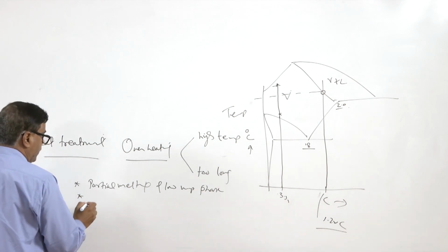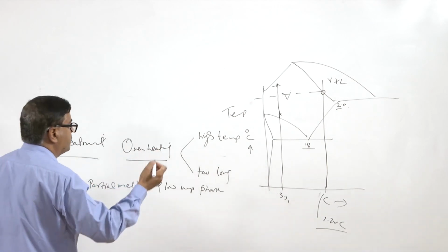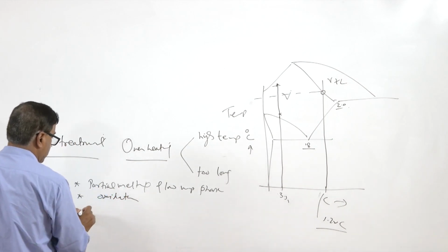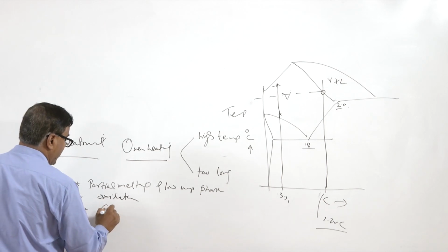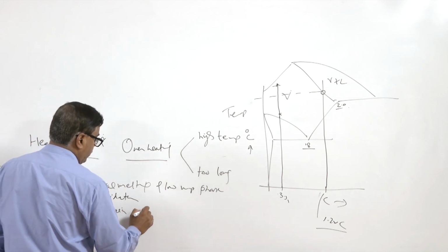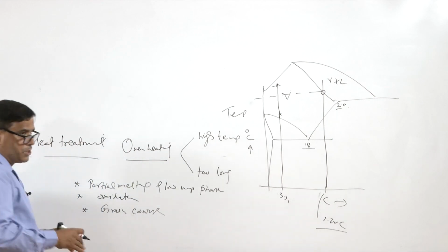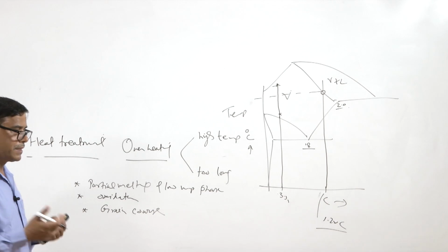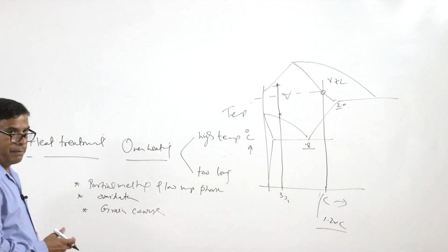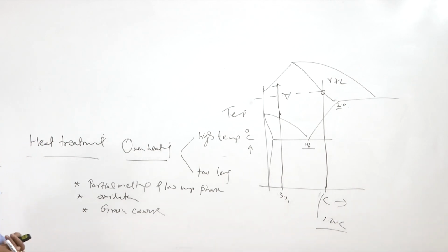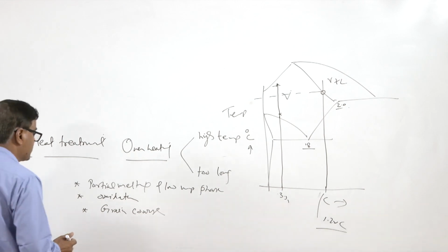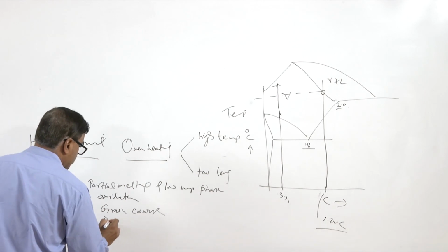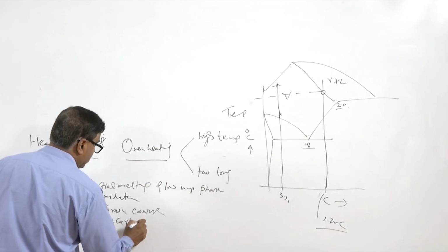Apart from this one, heating to a high temperature for long can lead to oxidation of the metal surface. It can also lead to excessive grain coarsening in the form of coarse-grained austenite, which can increase the hardenability and produce martensite in place of the fine pearlite which would otherwise be needed. Excessive prolonged heating at high temperature can also lead to decarburization.